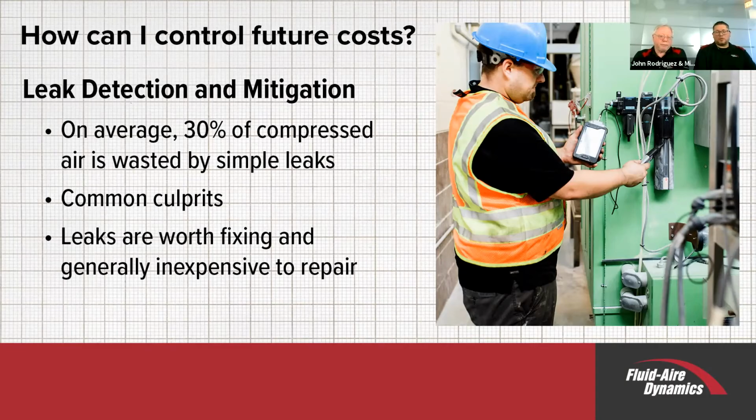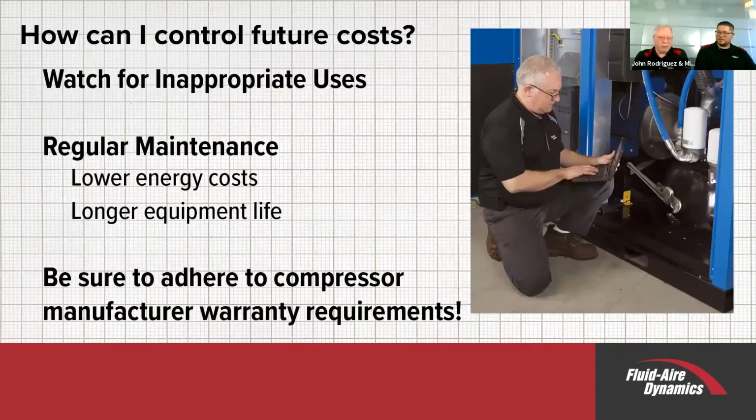The other thing is that you should maintain your machine. A machine that's not well maintained could cost you a lot of money as far as energy is concerned also. Oil should be changed at least, it depends on the oil manufacturer or the oil that's in your machine. Some are 2,000, some are 4,000, some are 8,000. Make sure you maintain that oil. After a year, by the way, on any oil, it should be changed because of the shelf life. But maintain it according to your book. Again, your filter should be changed. Your separator should be changed.